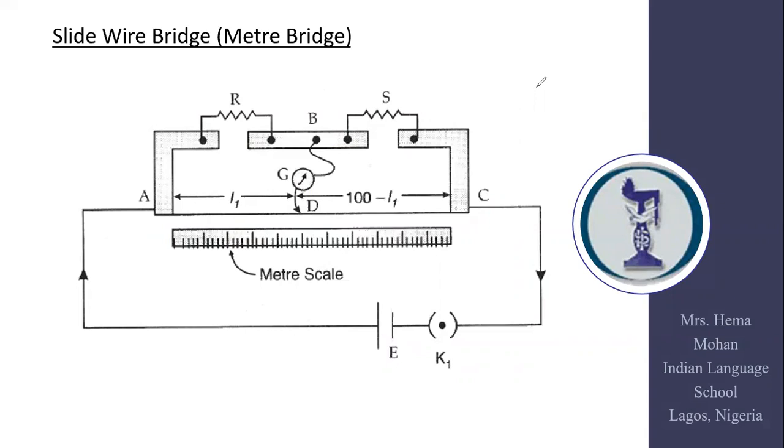So that is why this meter bridge is also called a null deflection method, because you are achieving the bridge balance condition when the galvanometer shows zero deflection. Now, you are going to measure the length of the wire under bridge balance condition.